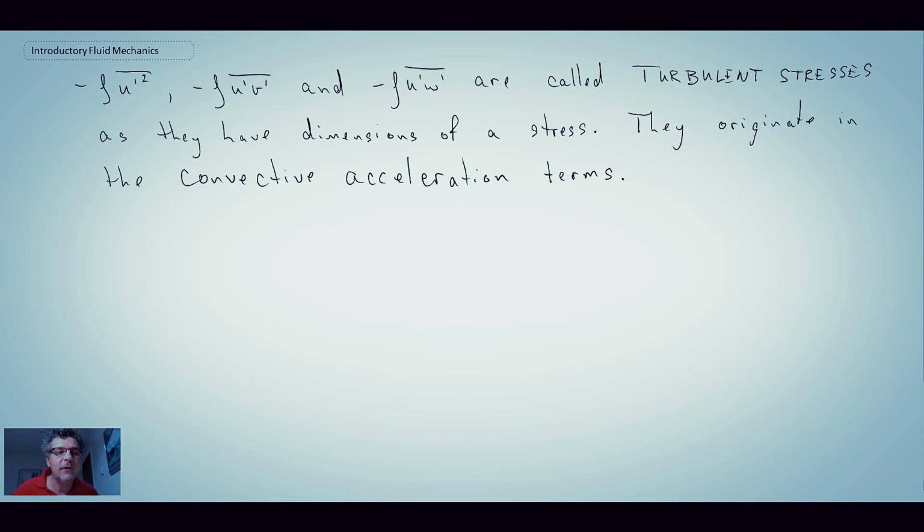Okay, so we have these terms, and these are turbulence fluctuations. People worked with these governing equations for years and years, and there are different theories trying to come up with a relationship between these and mean gradients that would be within the flow field. Because in order to solve for the velocity profile, you need to know these, but you need to know the fluctuating components before you can solve for them, which makes it what they call the turbulence closure problem. It was how you come about determining what these different fluctuating components would be.